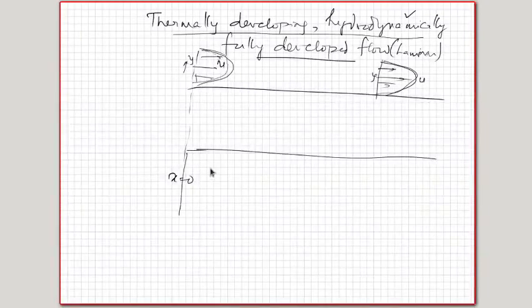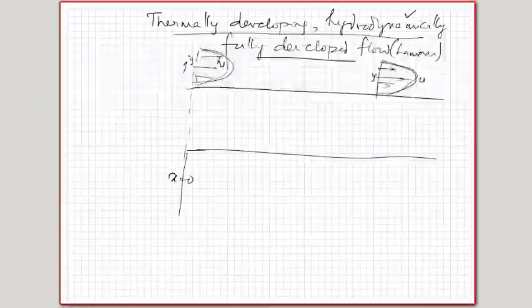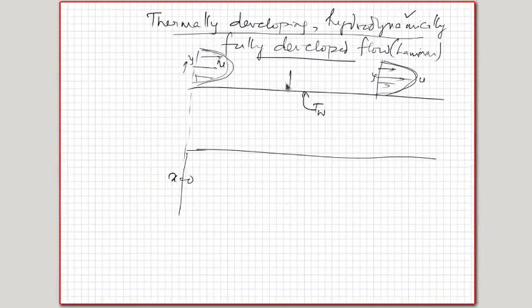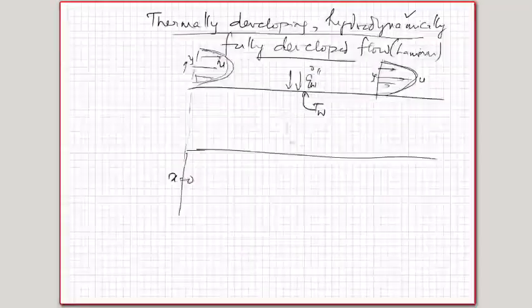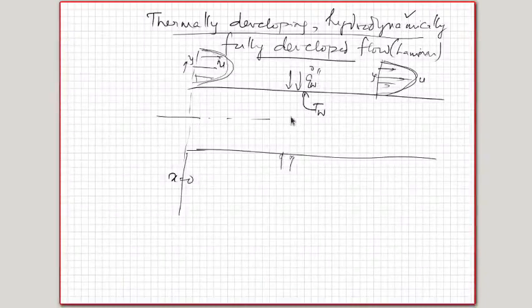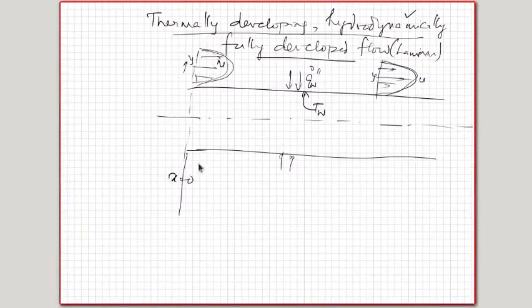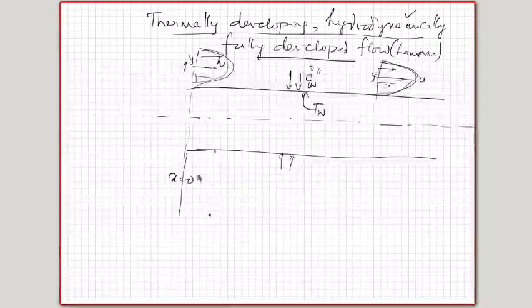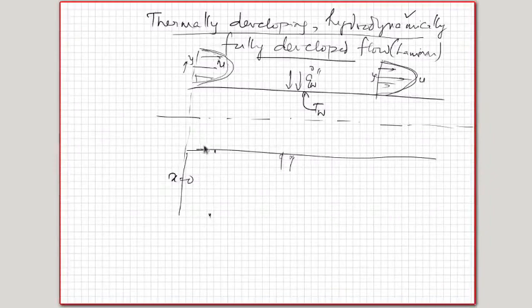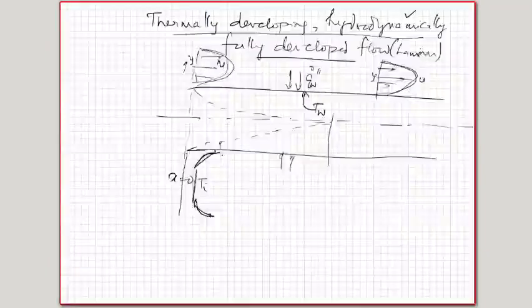But the temperature profile, let's show it below. So suppose I am looking at, let's say, constant wall temperature, or it could be variable wall temperature also. So let us say T wall is the wall temperature, and let's say Q dot double prime wall is the heat flux through the walls, and let's say this is the center plane. Okay, so then the temperature profile, let's say it's constant wall temperature, and let us say the inlet temperature is Ti, then at the inlet, because of the kind of velocity profile, temperature profile development, in this region there is a certain thickness over which the temperature profile is changing between inlet temperature and the wall temperature. Okay, so there is a variation from inlet temperature to wall temperature, and then the rest of the region, the temperature is equal to Ti. Let's say this is Ti and this is T wall.